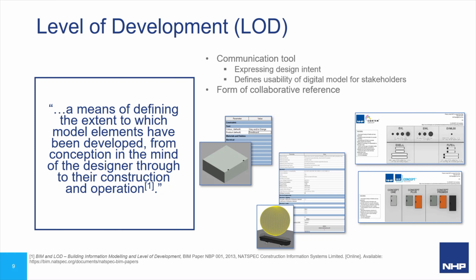Imported 3D files can on occasion contain too much graphical and geometric detail of an object. This can affect the processing speed of Revit depending on how powerful a computer you may be running. If you do not require such detail, all you are doing is wasting computational power trying to maintain such level of detail. On a large building where you may have 2000 GPOs, 300 lighting fixtures, 500 tables, all detailed to as-built levels of development, you could have made a matchstick model of your building by the time you wait for your project file to actually open.